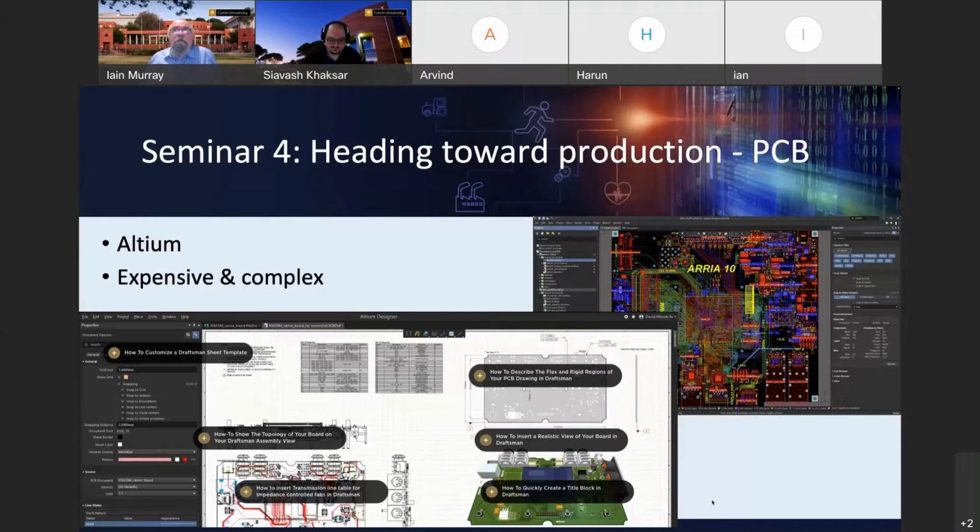It's incredibly complex to use. We have Protel come in and give courses to experienced PCB designers in how to use Protel, Altium. Part of a deal we've got them where we get free licenses. But it's a week training for experienced PCB designers to learn how to use their platform. It does the 3D rendering of your board design. It has all of the features. It also will do some frequency measurements, so looking for crosstalk on tracks. It will give you the correct weighting for the current draw of components and many other things, and auto routes quite nicely on its own.